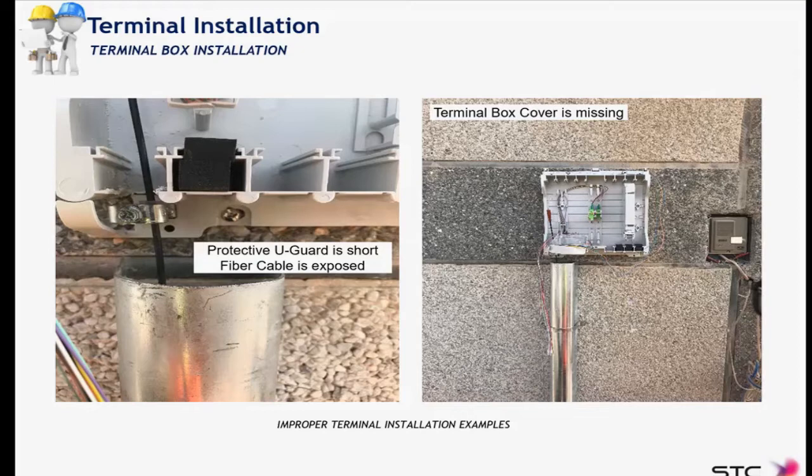In this case, both photos are coming from the same installation. The exposure here comes from the lack of cover, but even in many other cases with the cover installed, we see in the field that this gap still exists. So pay special attention to that when installing the terminal boxes.